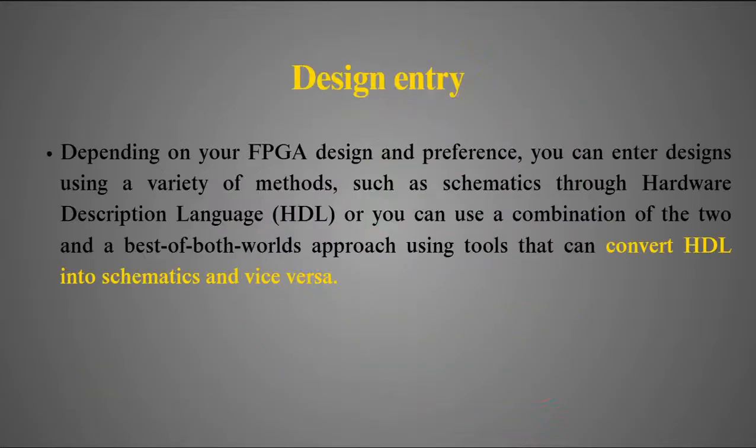First, design entry. Design entry is nothing but giving instructions to the FPGA. For that we have to write Verilog code or HDL code. If you are using a tool like the Xilinx tool, that particular tool will convert the Verilog code into schematics like logic gates.